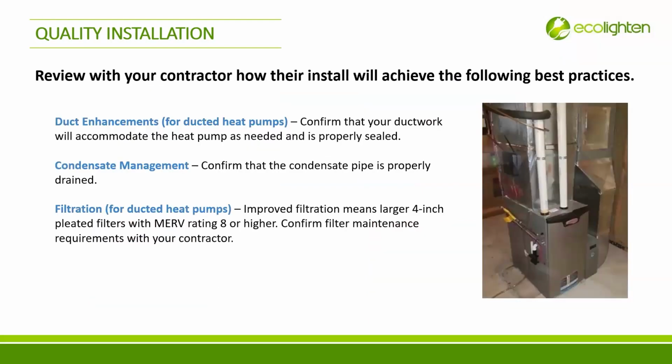Rob, there's also one other thing in the refrigeration world that they've discovered: sealing the end of the line set insulation with some silicone or tape so moisture can't get in the ends can actually help prevent pinhole leaks. They're finding there are a lot of refrigerant leaks that they're not able to source, and what they're finding is moisture getting into the insulation going into the line set is causing the copper to break down, like you see the discoloration in that copper line.